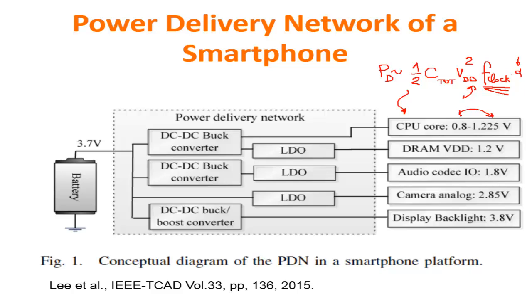And this is the reason why you have typically this range. Okay, this would be full throttle, so maximum speed, and the other one would be a situation in which you want to reduce power consumption. So more or less what happens is that the dynamic power, including the dependence of the clock frequency on VDD, is proportional to VDD to the third power.